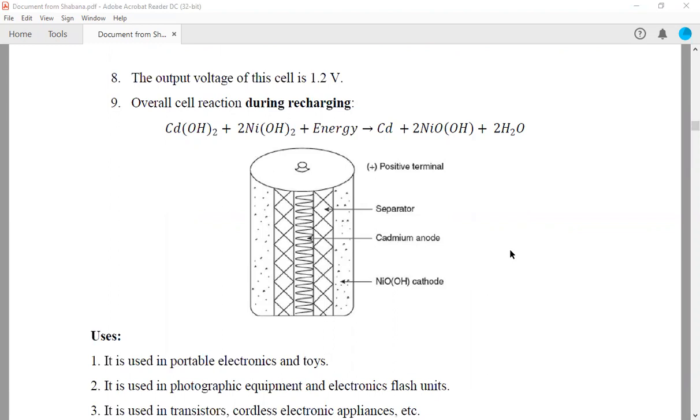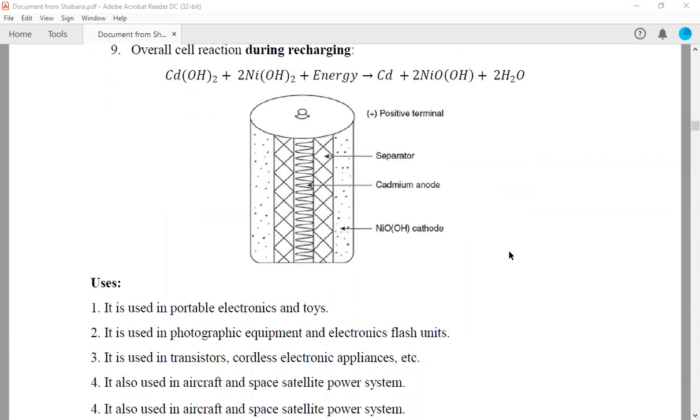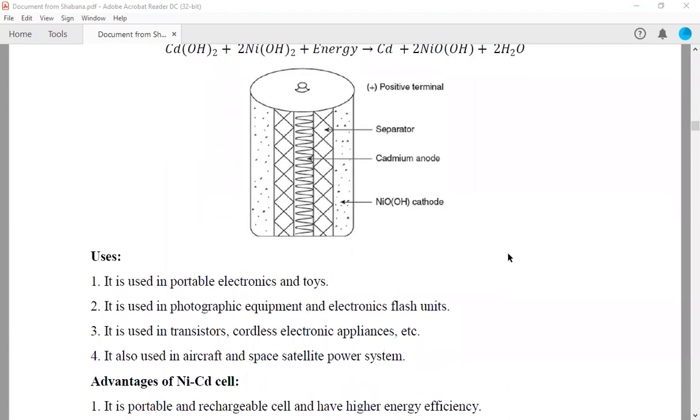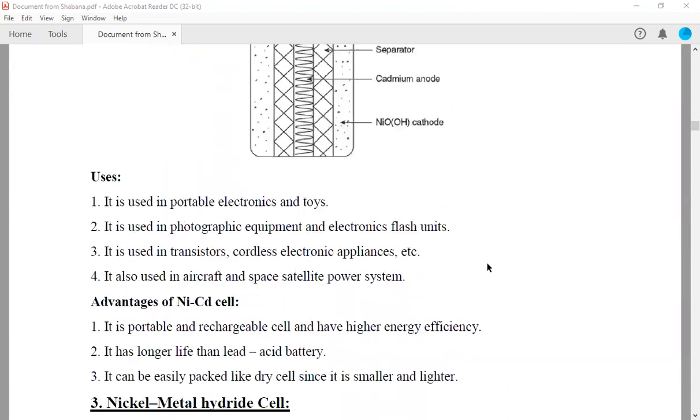Here, the advantages of the nickel cadmium battery are: the potential of the cadmium anode is below the hydrogen potential. Hence, the cadmium electrode is completely inert to the electrolyte. It requires no float current to keep charged.